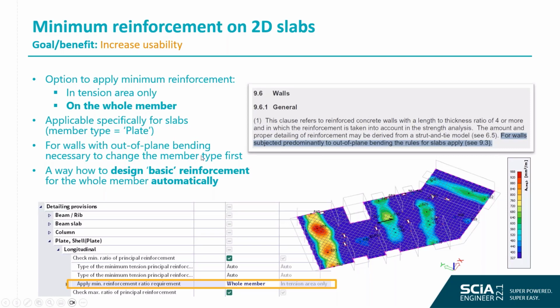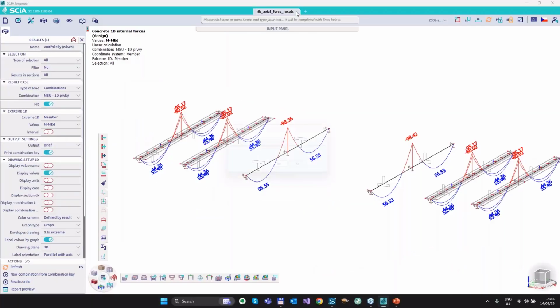And as a consequence, you can then completely design the reinforcement just using the additional bars in the design template, because since the reinforcement is on the whole member, at least the minimum one, the provided reinforcement is also designed everywhere. The option basic reinforcement, of course, you can use to manually input your preference, but if you want, for instance, basic reinforcement to be designed automatically, you can just play with the additional bars. So we will now jump to the live demo.